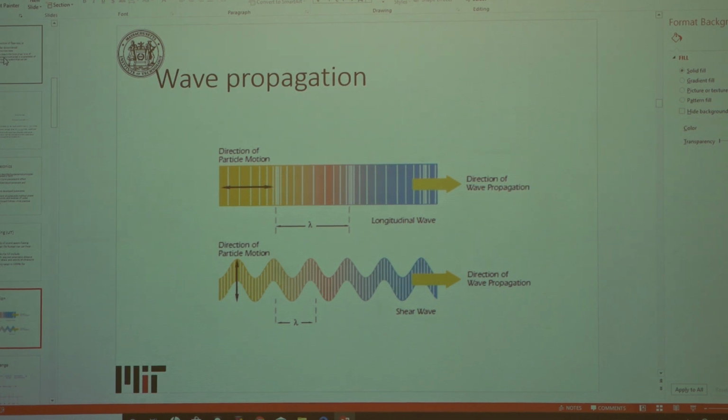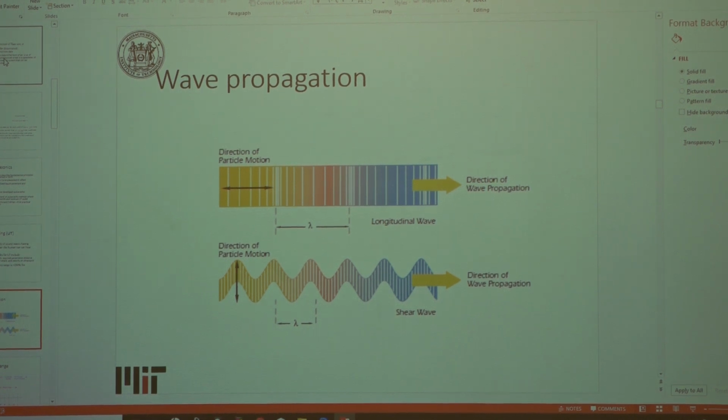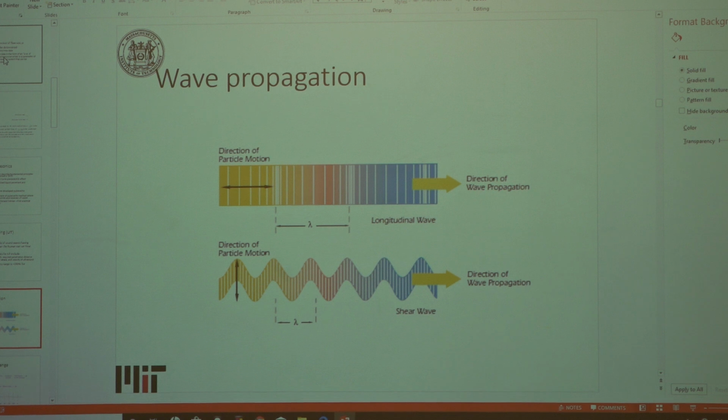I'll hand this out. This has some information on your question related to transducers, and certain transducers operate in certain ranges. One of the other things tying into your question is that if you wanted to use a transducer at over 100 megahertz, at some point you have to change the piezoelectric that you're going to use. So you have to design an entirely different transducer if you were searching for a delamination in a carbon fiber versus if you're looking for something in metal.